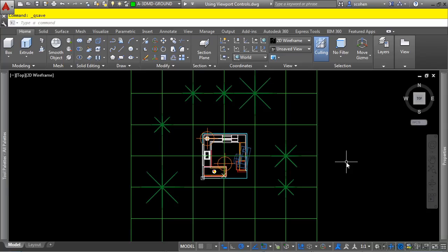So let's talk about the options available for creating and configuring multiple viewports and the overall procedure to change viewport display in model space. When working in 3D, you can increase your productivity by changing the number of viewports displayed within the drawing area. By creating the appropriate number of viewports in the right viewing directions for the task at hand, you can view the model from multiple directions at the same time. You can leverage this functionality to start a command in one viewport, then click into another viewport and complete the command. So how do you configure multiple viewports?